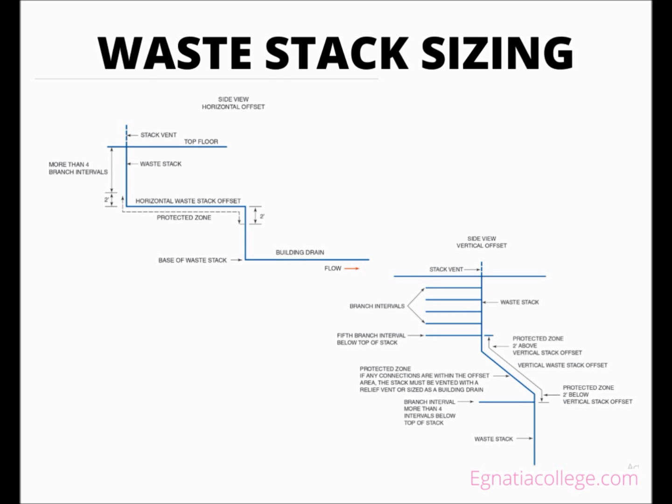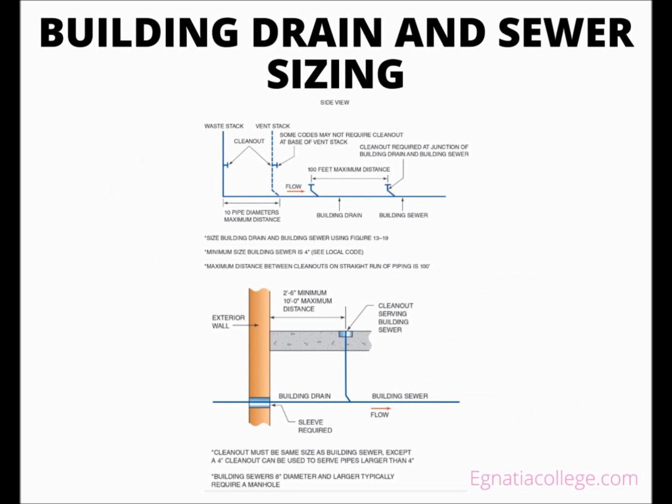Building drain and sewer sizing. IPC sizing methods for a building drain emphasize the importance of calculating all DFUs that it evacuates. Because a building drain is a major segment and the lowest horizontal portion of a DWV system, it has additional codes to adjust to variations in a project design. A chart lists general sizing scenarios, but additional codes are needed for unique situations that occur during the design or construction phase of a project.